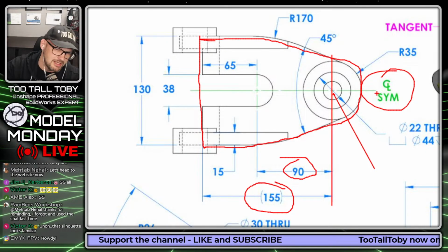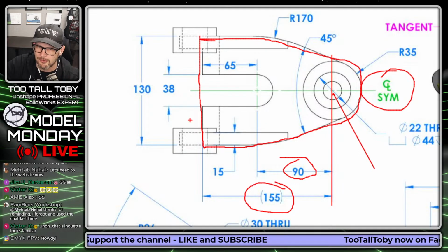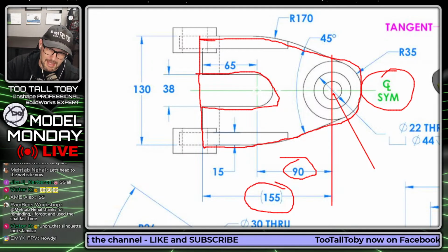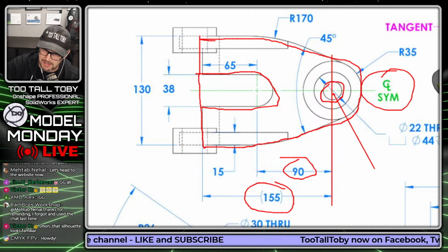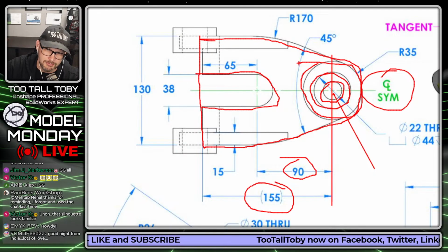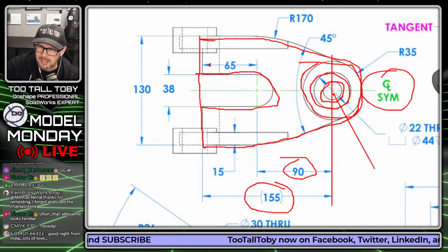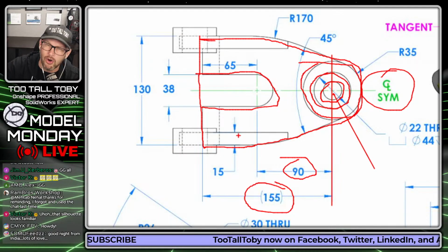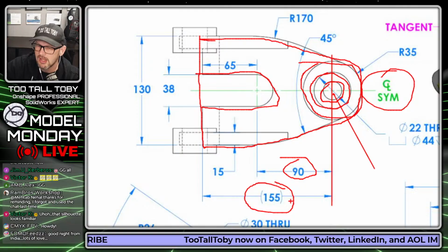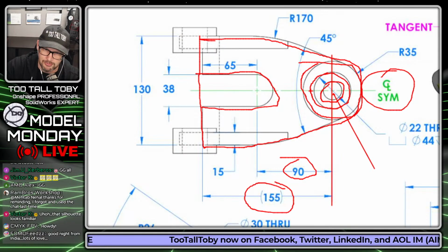So then the next question is, how much detail should I include in that first sketch? Because I'm working in Onshape, I'll probably opt to include quite a bit of detail here and then just extrude from these sketches. Certainly, if you're using a different CAD package, you could still use a similar workflow where you include all the information in your first sketch. It's just a matter of what you're comfortable with, and are you comfortable extruding multiple contours from the same sketch? In Onshape, I am very comfortable doing that.